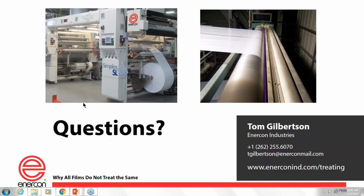All of these things, folks, that we corona treat, they're all carbon-based. And the corona treater's job, one of its jobs, is to affect the surface. And so we're going to chase some of that stuff off the surface to get the surface ready for converting. And during the course of that, some of those materials will plate out on the electrode or the surrounding area, and they will revert back to their original form, which is carbon. And if that occurs and you don't clean it off, carbon is conductive.